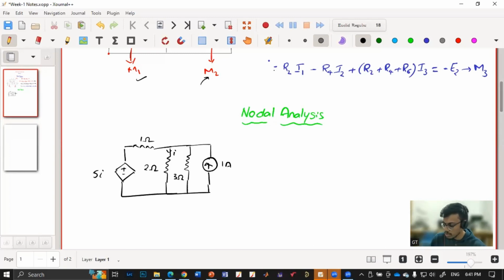So the voltage of this source is a function of the current in this branch, and it is 5 times that current. So I have to consider this as 5I, write whatever KVL or KCL equation, and then solve for I. Whereas if you consider this 1 ampere, irrespective of whatever circuit I am connecting here, this is still 1 ampere. So it is an independent source, and this is a dependent source. If you still have some confusion, sir will be discussing it in the upcoming lectures, and you can understand it better there. If you are still facing issues, we can discuss in the problem solving session.